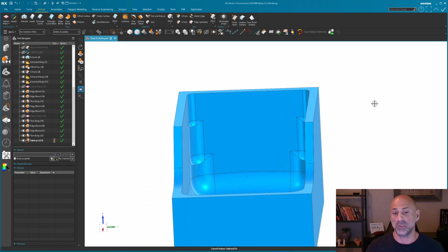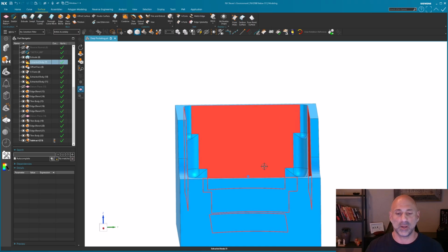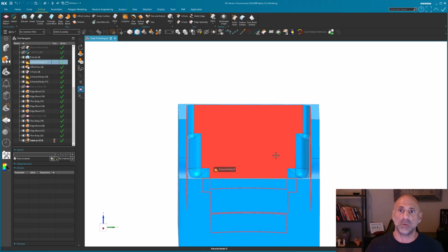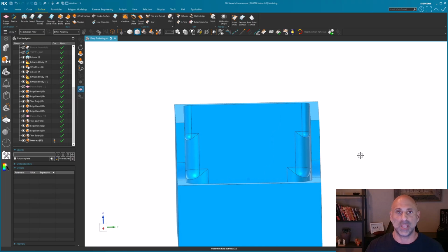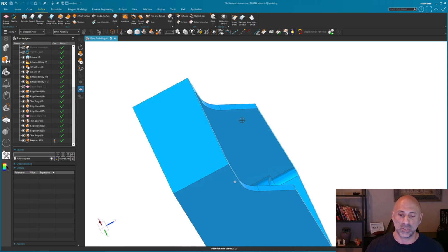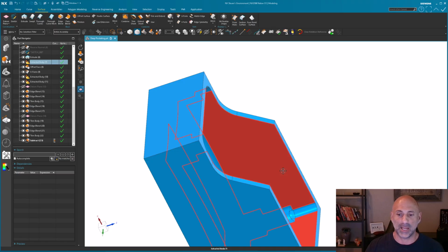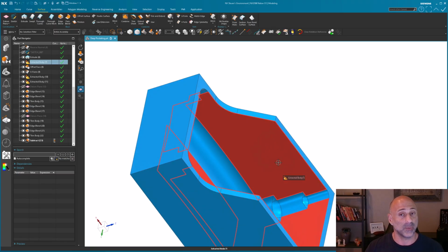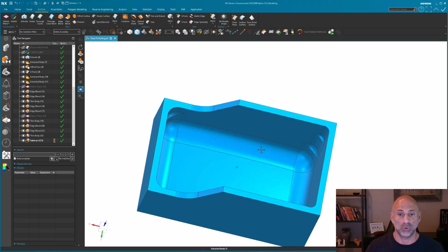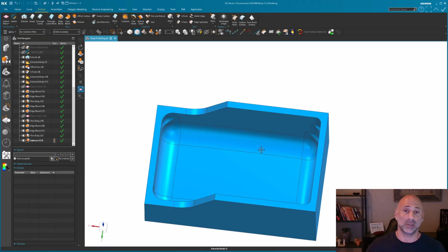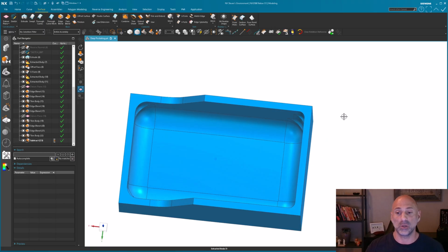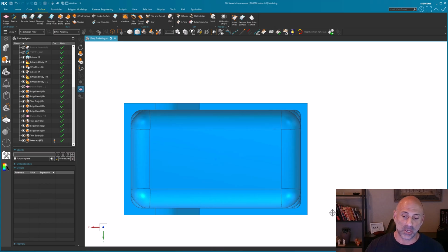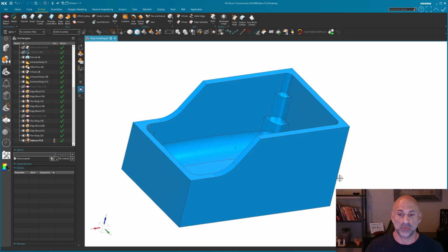And some people say, well, why don't you just get a 6-axis mill and come in at a very odd angle? Well, maybe you can't. Maybe you don't have the ability to get into that space because the tool holder or whatever can't come in that direction. Or maybe it just adds too much time because now you're doing another setup, coming in at an odd angle, and again, matching this face to make it perfect is going to be very, very difficult. So stuff like that is unrealistic. Truly, it's unrealistic. You really don't want to rely on that. So this type of thing seen in corners is far more realistic.